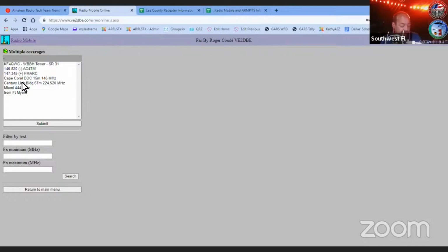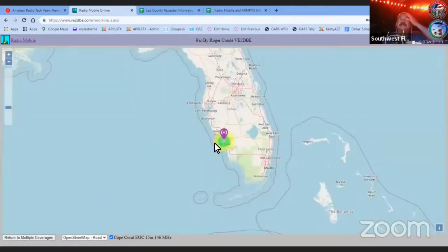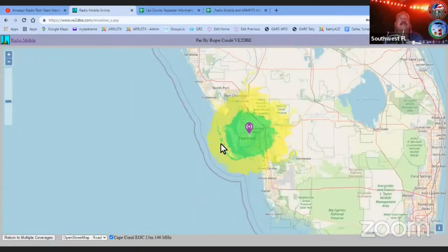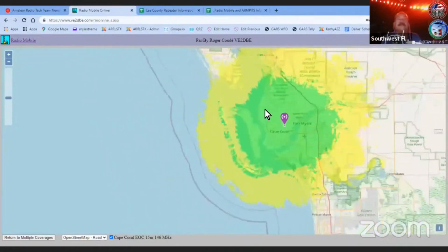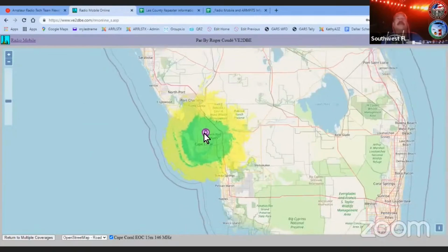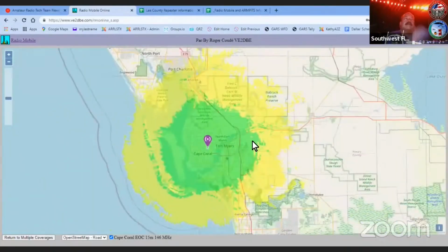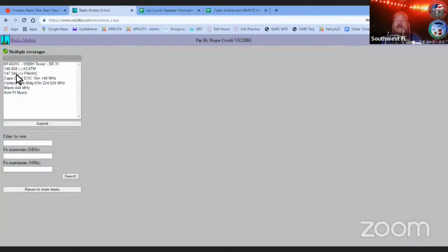This little radio works great, and I can hit that 220 repeater from just about anywhere with it. Then, in the shack here, I built a little dipole antenna out of a piece of wood, measured it for 220, and stuck it outside with a little SMA wire that comes in and hooks up to the top of this. It Velcros down in the charger, and I have a little breast mic that goes on it, so I can use this as a little 220 base radio if I want. But anyway, 220 is a good band.